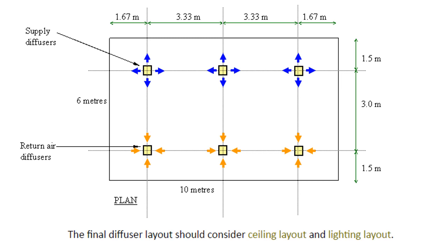And the arrangement of the diffusers is also very important, because you would want to distribute the air evenly, and you do not want a space, for example at the corner, to suddenly have no airflow.